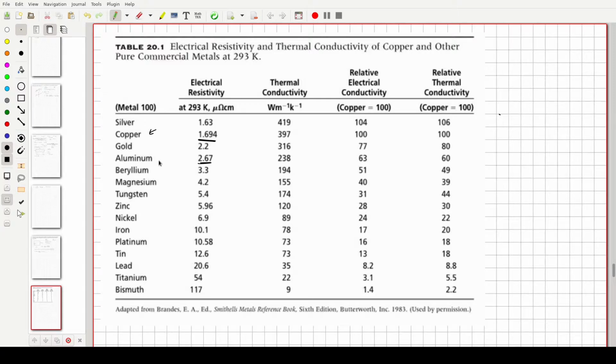That's because aluminum isn't nearly as malleable or ductile as copper. As your house expands and contracts due to normal heating and cooling over time, your aluminum stresses and fractures and causes shorts. And when you have shorts, that can cause electrical fires. Also, the stuff that the aluminum wiring was wrapped in is just horrible.